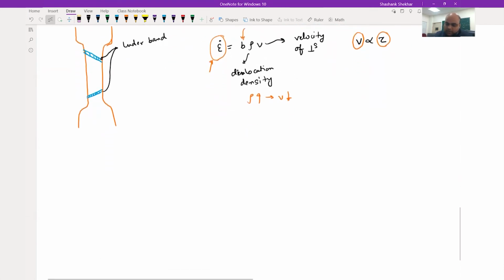Okay, so you have something like this. Okay, so you saw already upper yield point. Now this is lower yield point. Okay, and this lower yield point is happening because of the reduction in the stress to maintain constant strain rate.